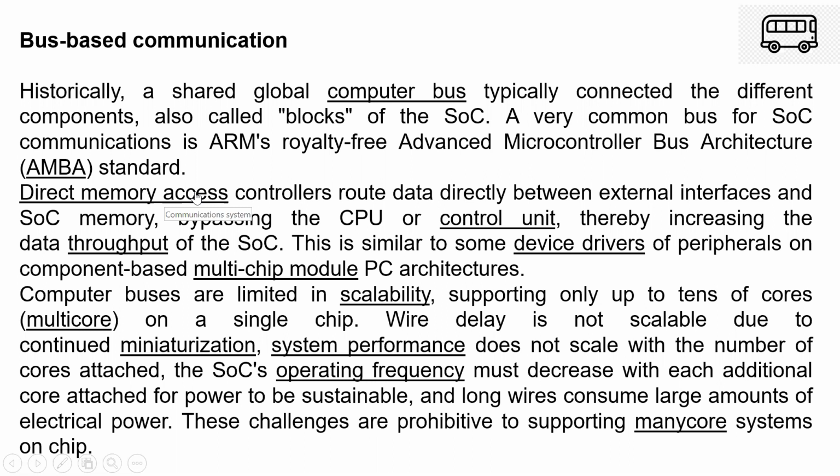All the CPU does is initiate the direct memory access and then leave control over it, and dedicatedly the external interface and internal memory communicate with each other and transmit and receive, or exchange, the data. So this is available with direct memory access. Okay, so as you can see,